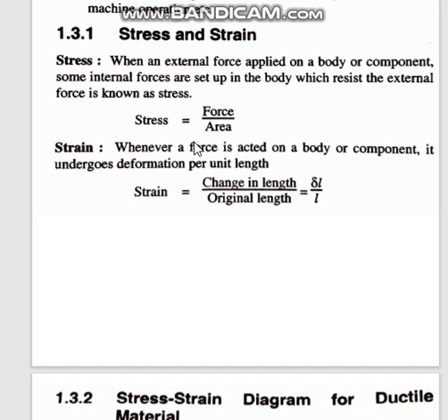Mathematically, stress is defined as force upon area. Force is normally given in newtons, and area in meter square. So this is Newton per meter square, and that will be the unit of stress.